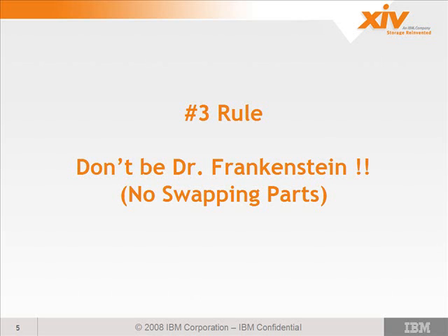It may sound like a good idea when you're in the field and it's 2 a.m. and you want to go home, but refrain from swapping parts on any of these machines. Ian pointed out during his overview some certain no-nos that you don't want to do. Compact flash has information that you don't want to lose. You definitely don't want to swap compact flashes between modules. You don't want to swap ports on a switch. You don't want to swap.